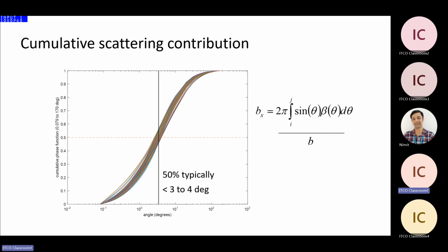Because that beam, when it goes through collimating optics on both sides, you're focusing it down to a pinpoint in a field stop, with a detector behind it. And it's very, very sensitive to that alignment. So when you move a prism back and forth, if you do it in a way where you can maintain perfect alignment, it can work. Or, another possibility is you get it configured the optimal way for the water that you're interested in making the measurement in, and then you calibrate it. You just don't move it at that point. You calibrate it, you make your measurements, et cetera, and you go through that process every time you want to change the prism length.